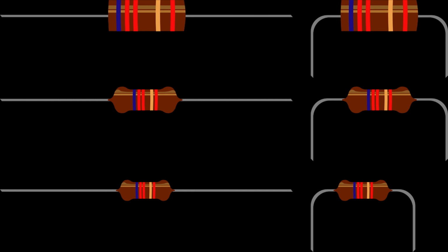You see that some resistances are thin, and some have more cross sectional area. Even if resistances have the same value, they are classified in terms of their power rating. So you cannot use this small resistance in an application where the power rating is more than a quarter watt.